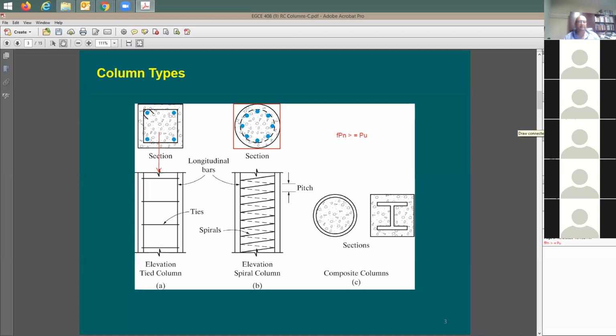In seismic, it's true that you're going to have shear forces, but in this case, there are no shear forces. Any other idea? Thinking about this? Maybe just to help not buckling. Exactly, what is not to buckle? Actually, the stem of the column, probably. Stem or these vertical rebars.